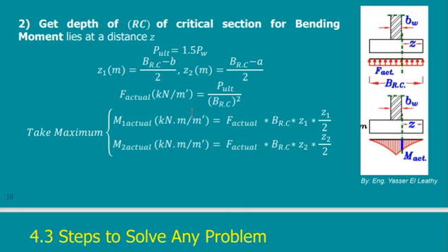So in my geotechnical code, we use allowable loads, not ultimate loads. I take the allowable load, divide it by the bearing capacity of the soil, how much the soil can take, and I get an area. This area will be the area of the foundation.